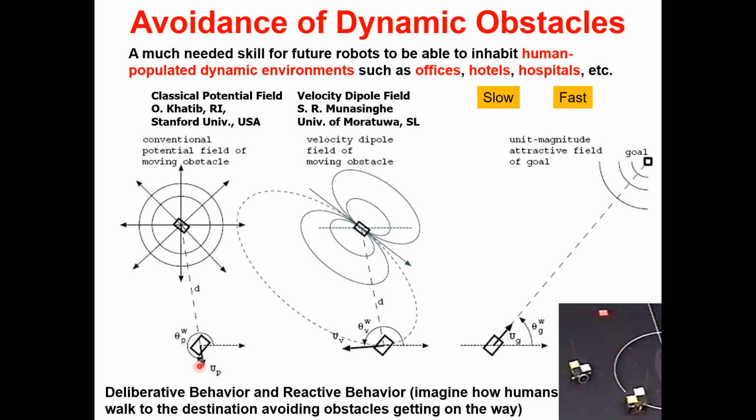So this is an artificial thing. There's no physical potential field. These are all artificial. Everything is happening inside a computer. And in the same coordinate frame, you generate this repulsive force, UP, and this is the artificial force on the robot. So if you are the driver, now you have to drive the robot and steer the robot towards UP. When you do that, you make sure you are not going to collide with the obstacle. So that is the whole purpose.